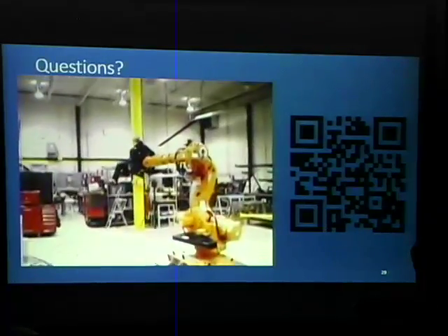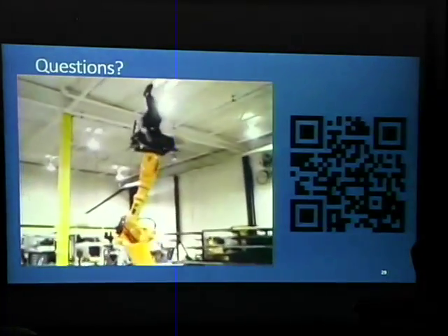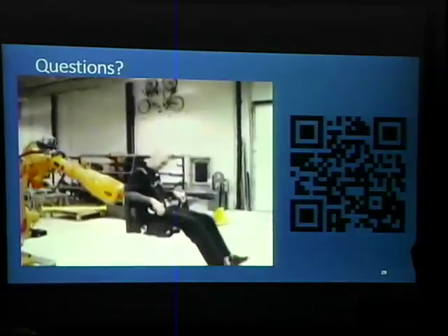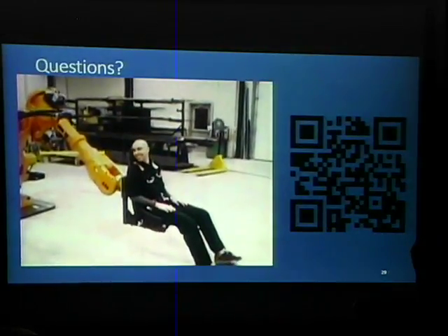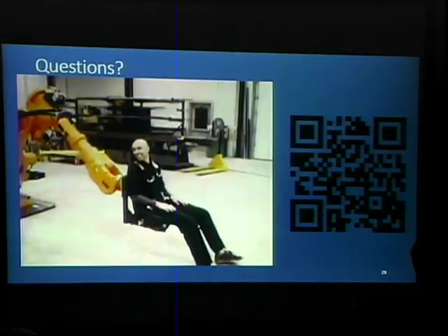And if you are still down in your hole in a big piece of titanium and you try and tell it to go to another location, the machine's going to go there, but it's going to leave the cutting bit where it was. So that's why you want to know what it's doing so you can understand what it's doing, but you want to try and avoid writing it by hand so that you remember to come out of the hole, because the software doesn't forget to do that.